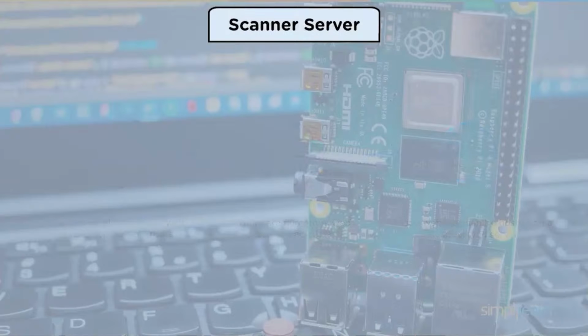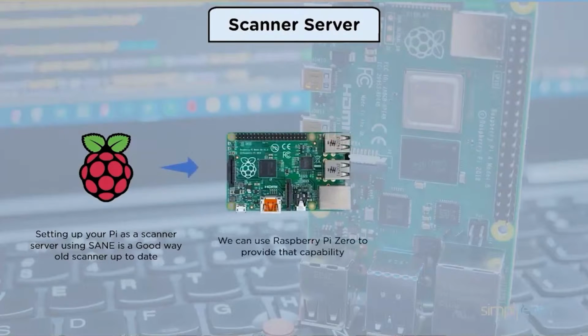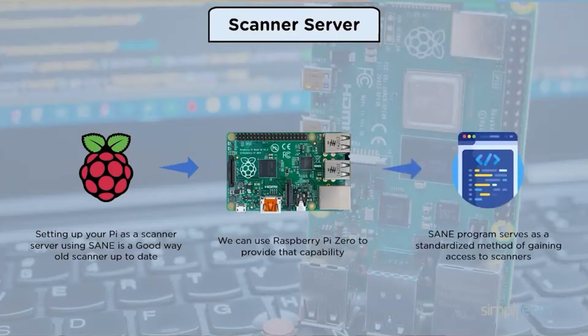Scanner server. Setting up your Raspberry Pi as a scanner server using Sane is a terrific way to bring your old scanner up to date. Instead of purchasing a Wi-Fi capable scanner, you can use a device like Raspberry Pi Zero to provide that capability. Scanner Access Now Easy is the acronym for Sane. This program serves as a standardized method of gaining access to scanners.